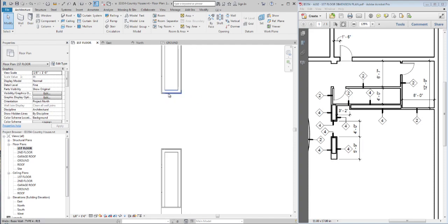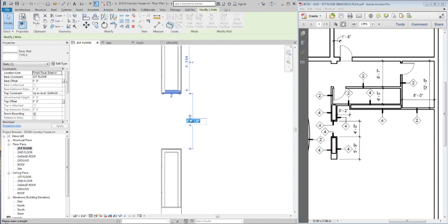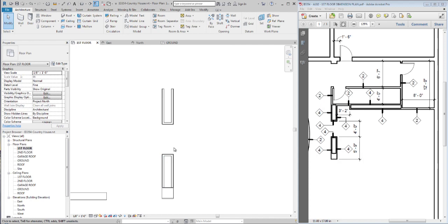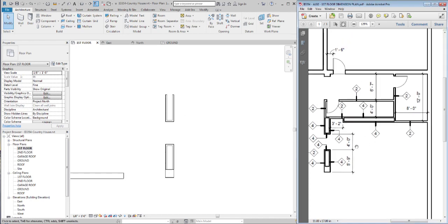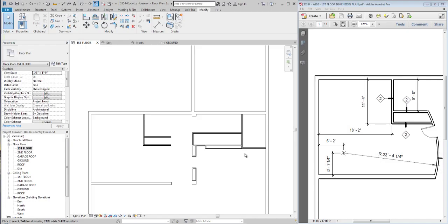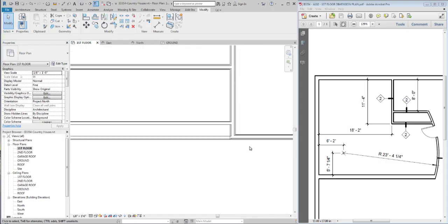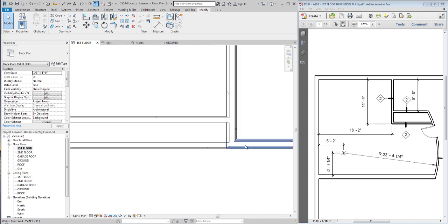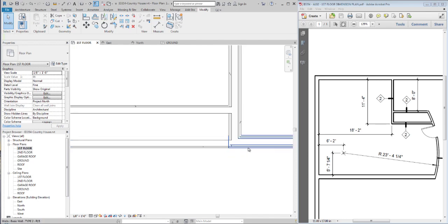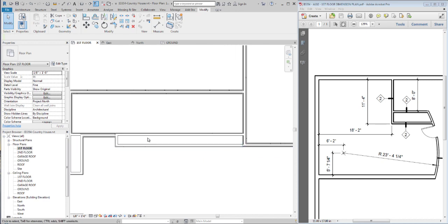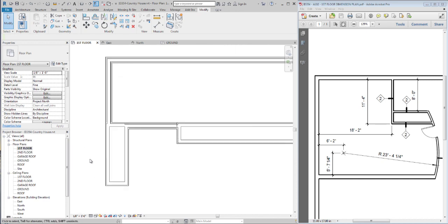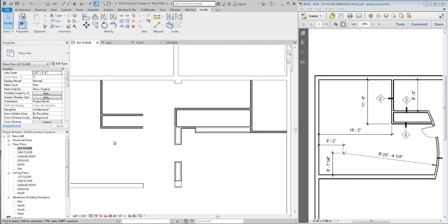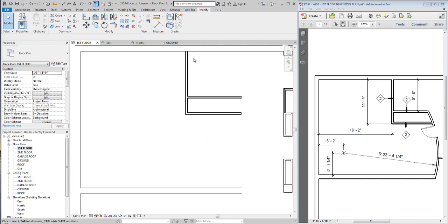So space bar and then make sure that you set the correct dimension in here. And then keep going until you build this entire thing. This is how far I got, and make sure that when you build your walls, they look just like this, that the sheetrock on every wall is on the outside. As you can see, these are all furring partitions, and the sheetrock is only on the finished side. And then on this side I got up to this point.